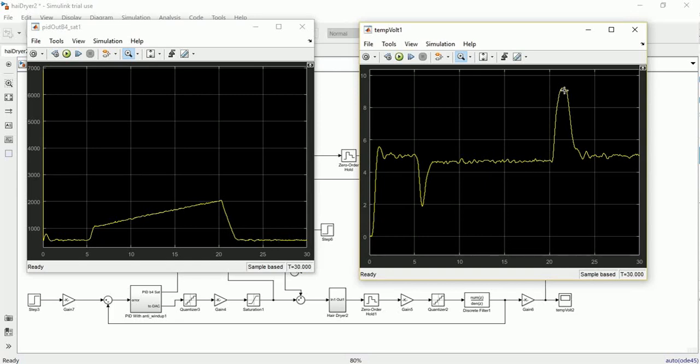This is why we have this big overshoot and the transient here. This is the explanation for this transient. So we know that the actuator cannot offer more than 10 volts. The integrator doesn't know that, and it keeps on accumulating, trying to reduce the error. But the error cannot be reduced ever, and then this accumulation will keep on going as long as the disturbance is there. And this is called windup.